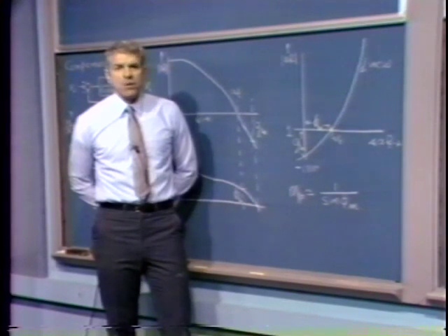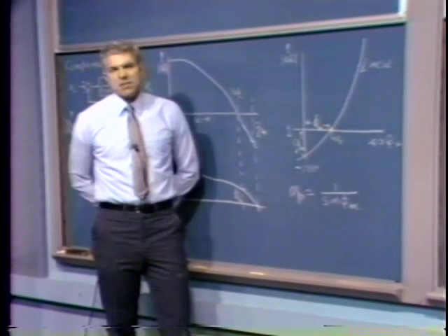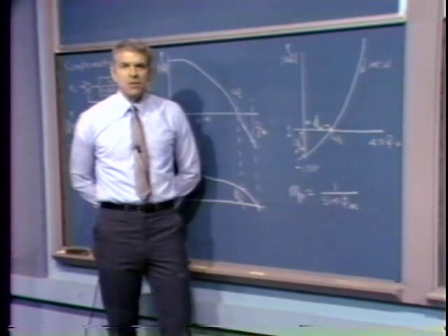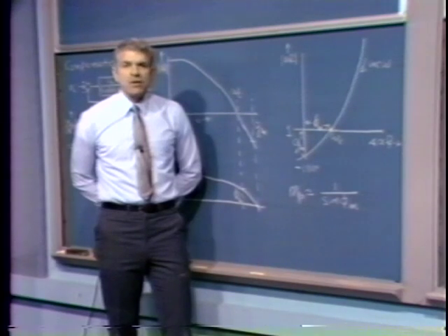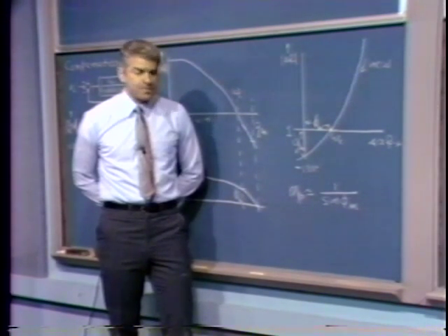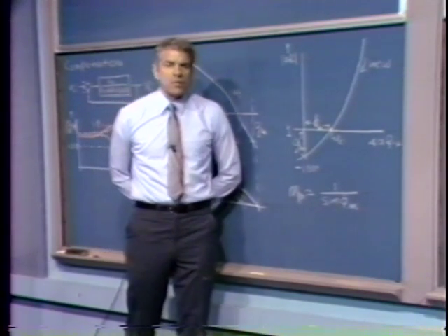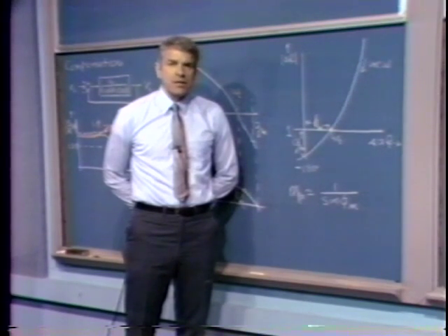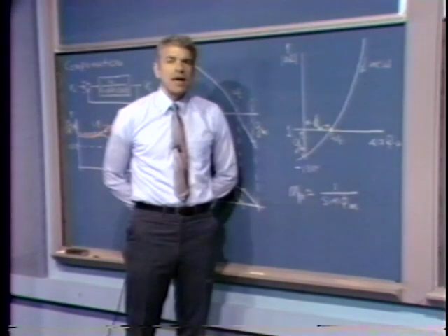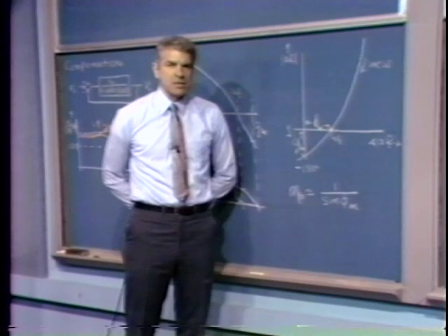We can go ahead and from the Bode plot determine, first of all, is the system stable? We can translate a Bode plot into Nyquist coordinates and determine rapidly if the system's stable. We're then able to evaluate the crossover frequency very rapidly. We're able to determine the gain margin and see if it's, quote, enough. And then we're able to find the phase margin of our system. Those constructions are very rapid and give us remarkably good results when we ask about the performance of a feedback system. Once we know the phase margin and the crossover frequency, we can make excellent predictions about the closed loop response of the system.